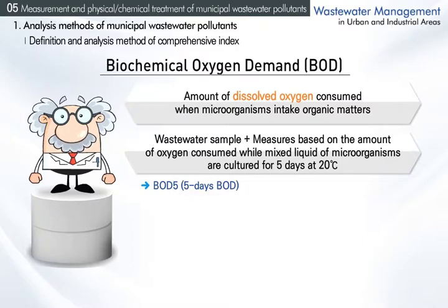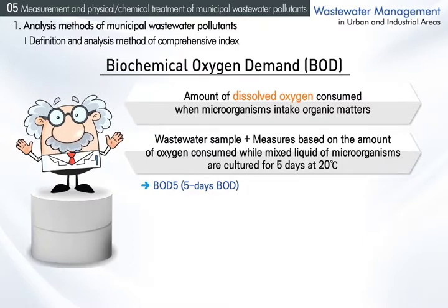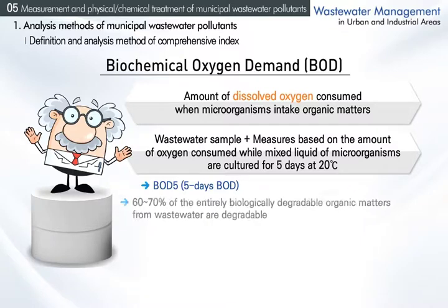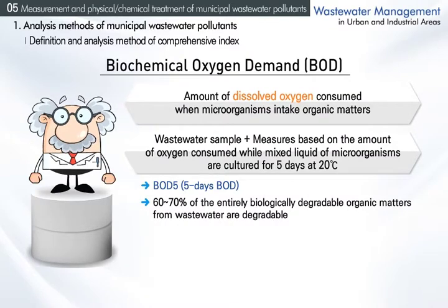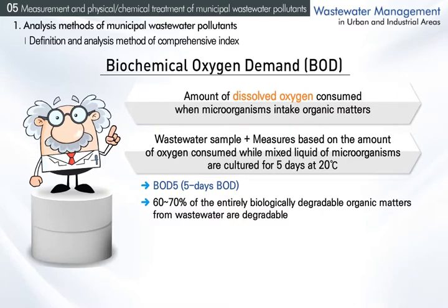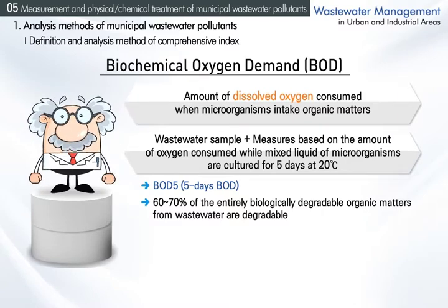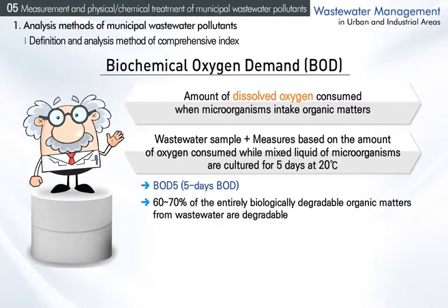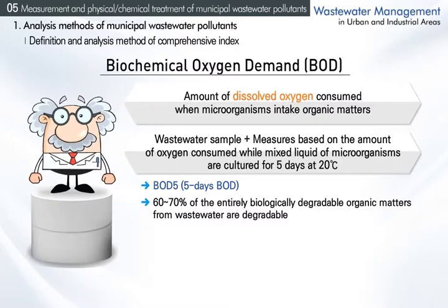It would be BOD3 if they are cultured only for 3 days, right? While culturing them for 5 days, about 60 to 70% of the entirely biologically degradable organic matters from wastewater are degraded. The period of culturing will become very long to find a BOD value near 100%.